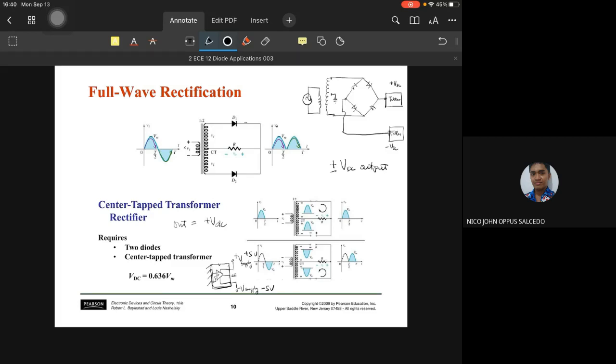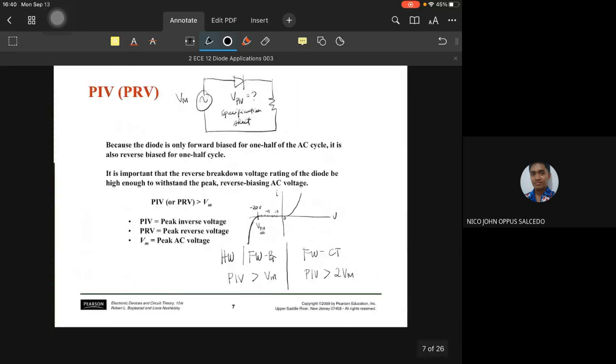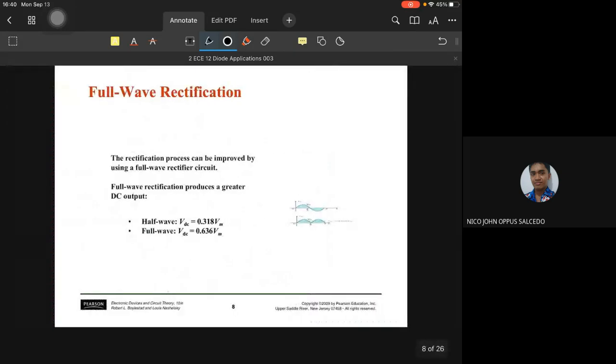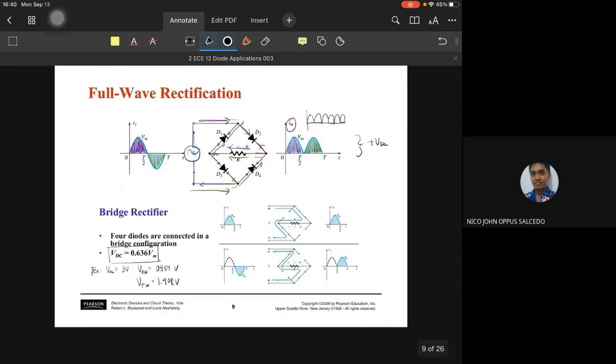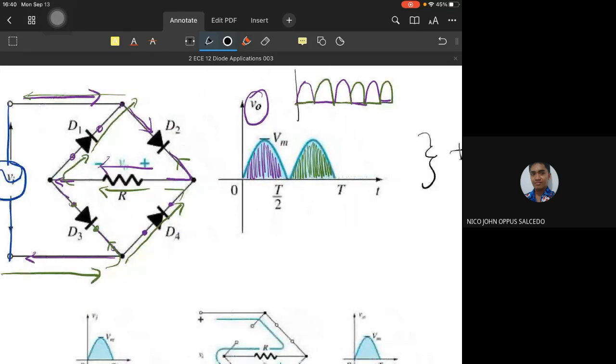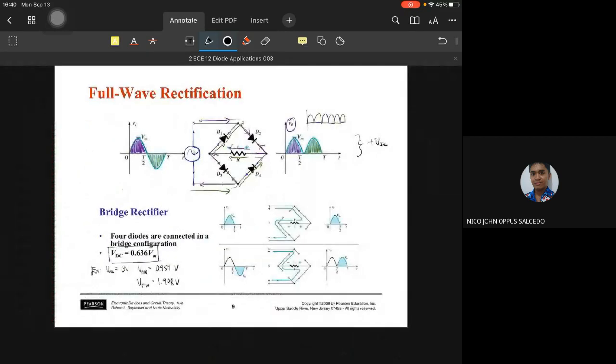To summarize what we've discussed, it's quite easy. A half-wave rectifier only passes through the positive half cycle of the signal, whereas a full wave rectifier passes through both the positive and the negative. And more than that, the negative half cycle of the signal is shifted up, so it looks like that. If you've understood that, we won't struggle understanding the other wave shaping capabilities of the diode.